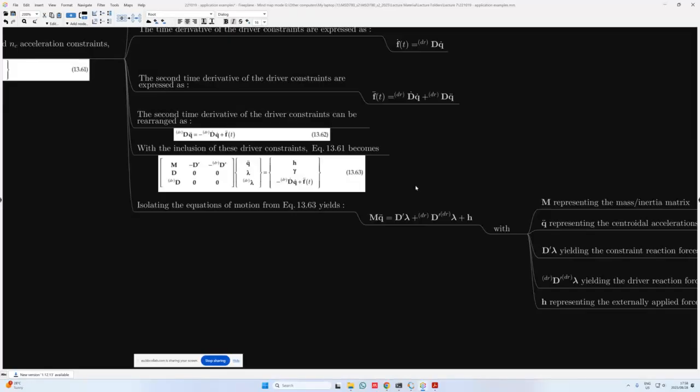Remember, up to now, we've considered revolute joints, and we said that usually we're just interested in the magnitude. But if you are interested in the actual sign and the actual impact that the reaction force has in the system, when you consider more complex joints, you need to also multiply it by its element within the Jacobian. But just take note that there's going to be some multiplication that we're going to do between the Jacobian and the Lagrange multiplier to extract that specific reaction force.